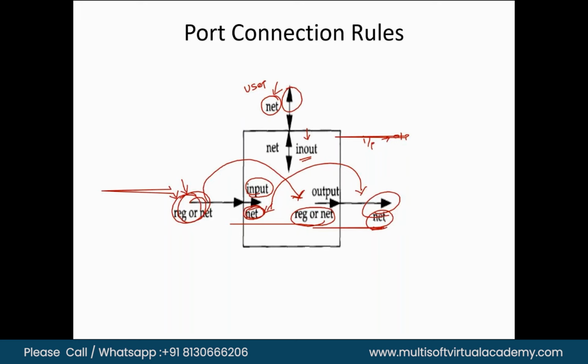While writing the Verilog code, when will we use a wire, and when will we use the reg type? Reg will be used in your behavioral modeling. And net is used in your structural modeling.